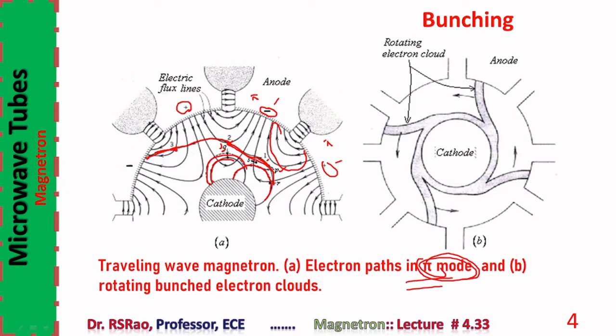Now one can understand easily why electron P is called a favored electron and electron Q is called an unfavored electron. All favored electrons come together and form into bunches, as shown in the figure. These bunches appear like spokes of a wheel, that's why they are called wheel spoke bunches.